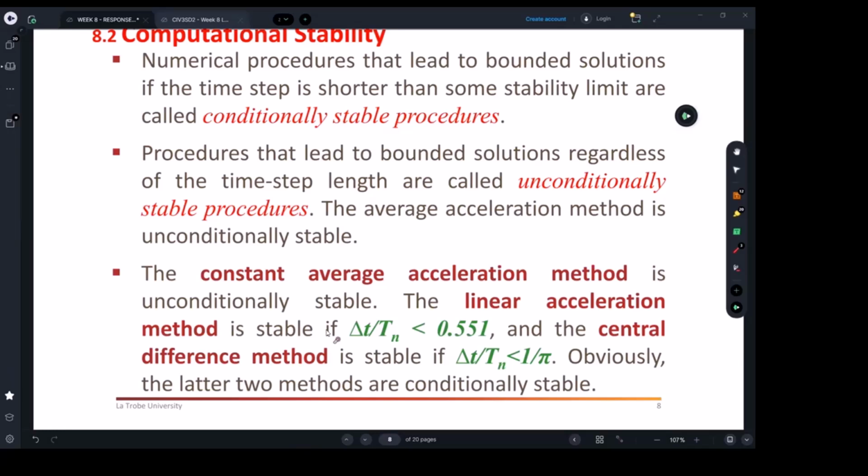So how you measure the accuracy is you keep reducing the time step until you start getting the same results. That's what we talked about with meshing last week. You remember when I started showing you how to mesh your RCB building model? Some of you may start with a 1 meter mesh. Some of you will start with a 0.75 mesh. You can try again at 0.5, half a meter mesh.